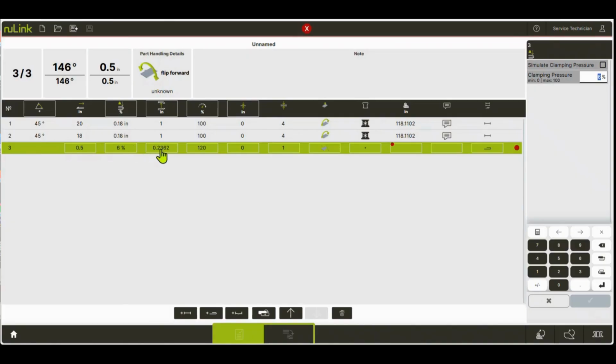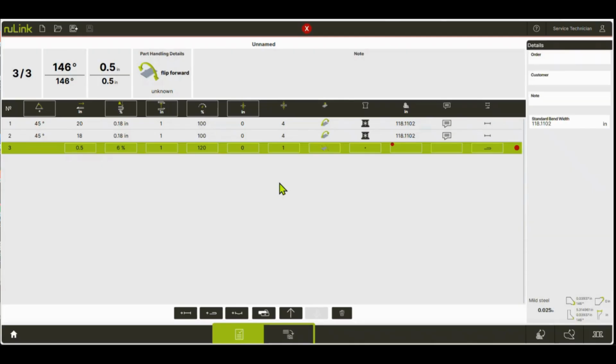And we want our clamp beam to go up at least 1 inch, right? So we can flip that part in. If you can do it without that, that's not a problem. Again, we can leave the default speed in there. It's thin material. This number carries down, because we don't have a machine in this setup that has that automatic movement. So this number just rides 0 all the way down the line, okay? And now we only have one part thickness put in there, right? So this number of plies stays at 1.